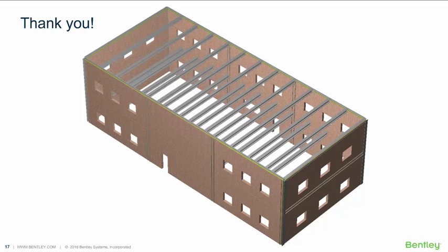And I think those are it. Let me see if there's more to this. How about, should the intersecting L or T walls be modeled integrally or with a gap? In the current project, there's a 6-inch gap and the T walls are rotated 90 degrees, but they still seem to act integrally and bear the majority of the axial component of lateral loads. Okay. Yeah, it's pretty much all or nothing.